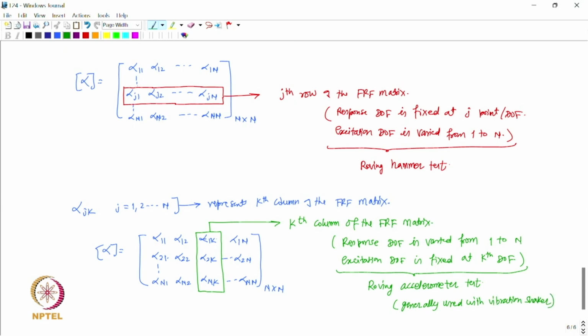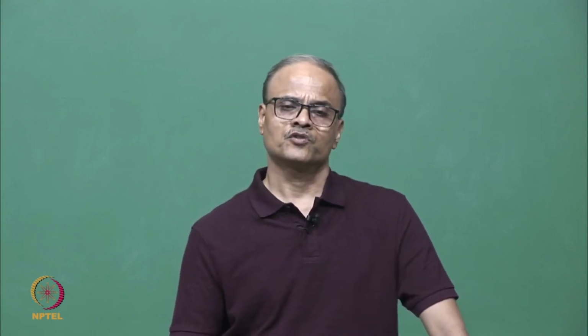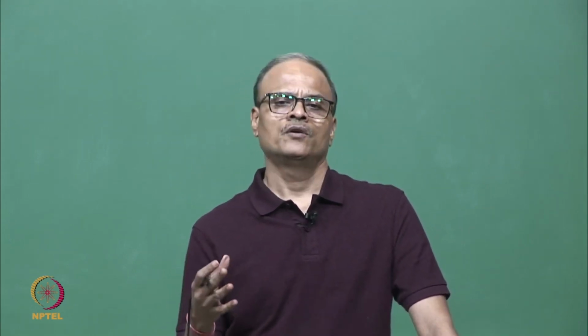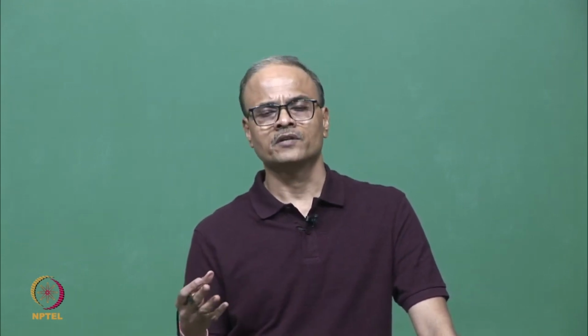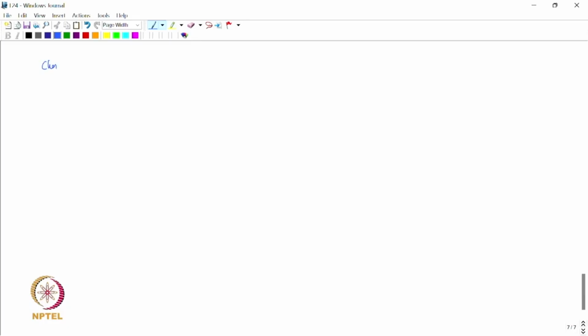Okay. So, another decision we need to make before FRFs can be measured is at what point the response transducer in a roving hammer test, or the force transducer in case of a roving accelerometer test, should be located. So, the choice of response transducer and force transducer locations.